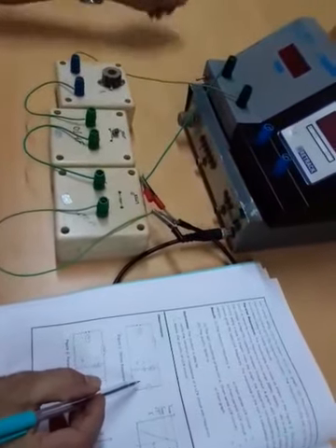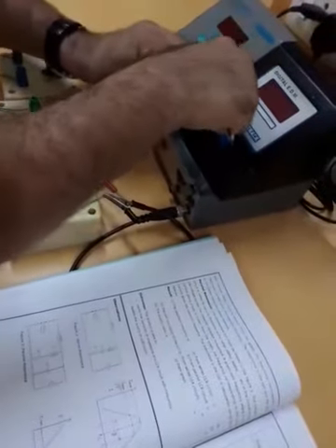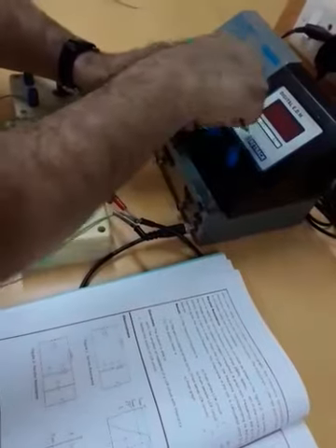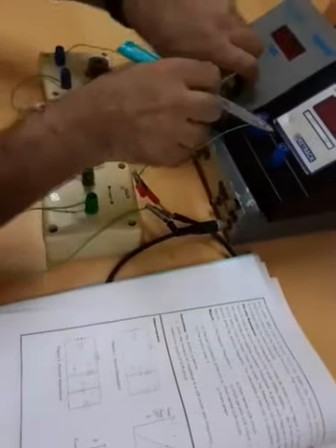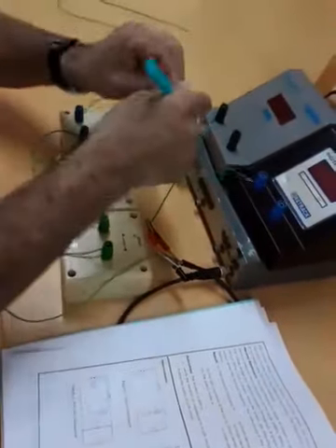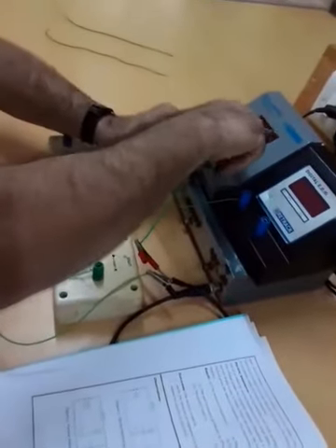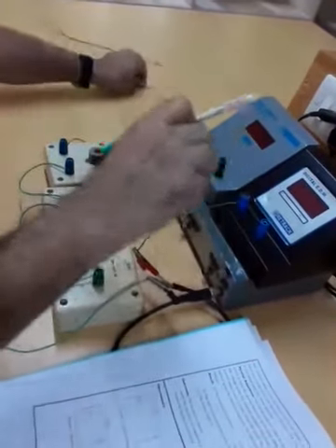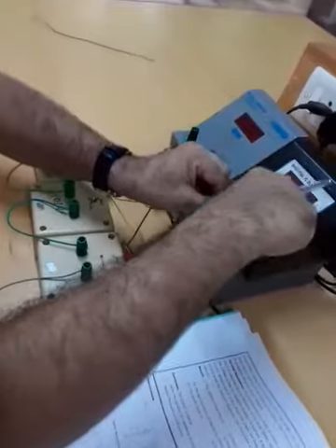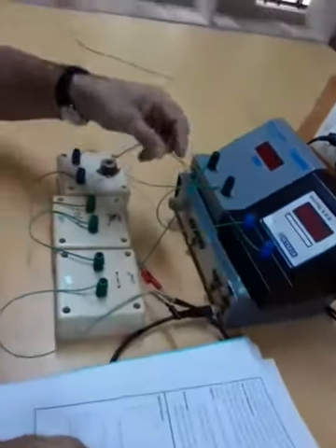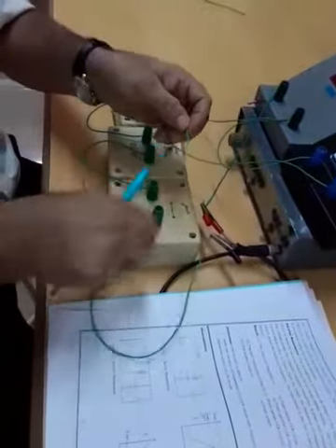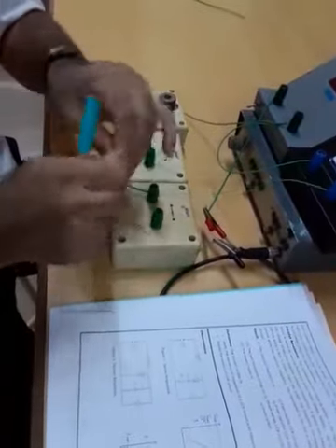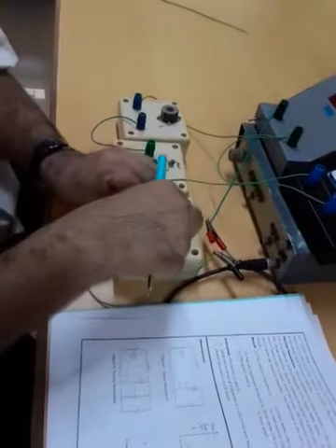Meantime we have a voltmeter. One end of the voltmeter is connected between the inductor and the milliammeter junction, so I can connect it together. And the other end of the voltmeter is connected to the resistor and signal generator junction. So I can connect it like this. This is the circuit connections in the series connection.